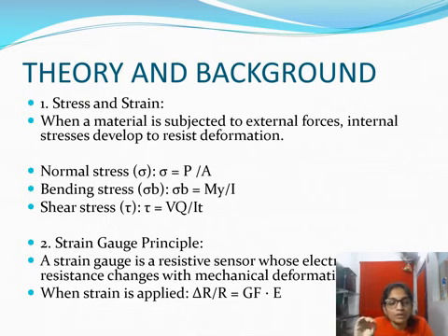Strain gauge principle. A strain gauge is a resistive sensor whose electric resistance changes with mechanical deformation. When strain is applied, the relative change in resistance is equal to gauge factor into strain.